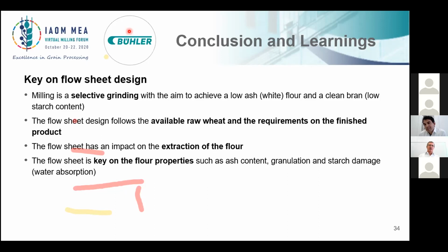Oh, it's very specific, and we would need to look at it. Consistency of wheat is important. Very often it happens that millers think that the wheat is consistent, but it can be the bottom of a bin. It can be, of course, the raw wheat bin, it can be the tempering bin, and always there is a segregation. It can be the best designed bin, there is a segregation, so the bottom of the bin can be different wheat. Usually it's a bit lighter. The heavy wheat passes fast. So it must come either from the wheat, which is not consistent.